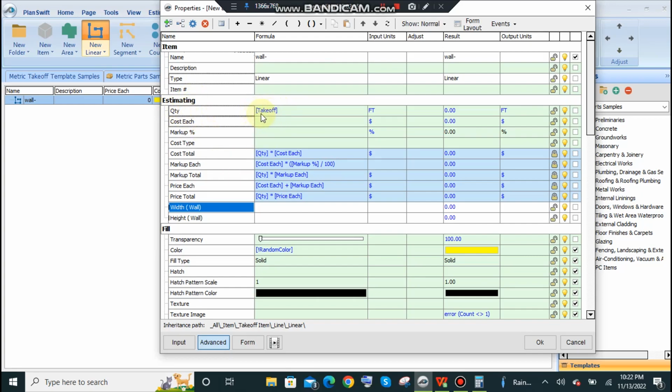So this is only linear takeoff, which means it is simply the total length of the wall. So edit it with a multiply with the width of the wall, then multiply it with the height of the wall. Simply drag and drop like this, and the formula will be according to your need, so add the brackets. Now this is saved, and the unit will of course be cubic feet. So select the unit as well. Now we will get the total volume of our wall.